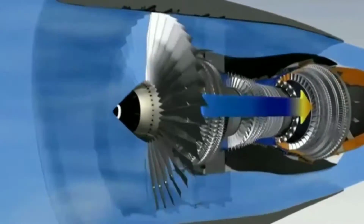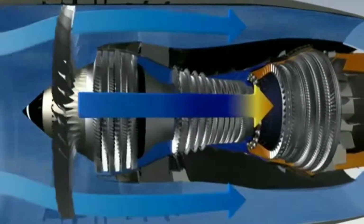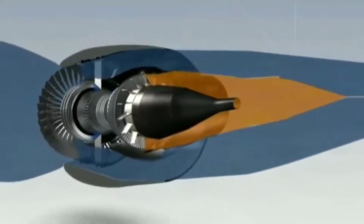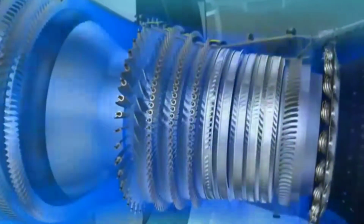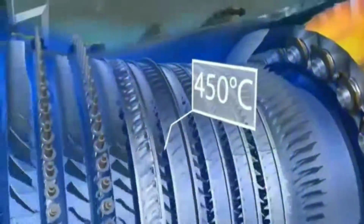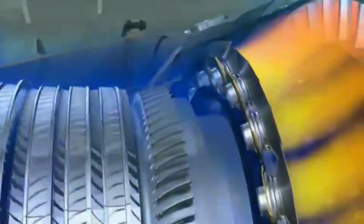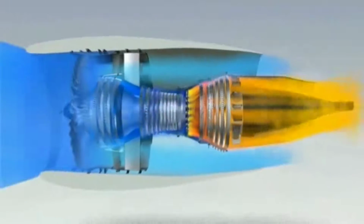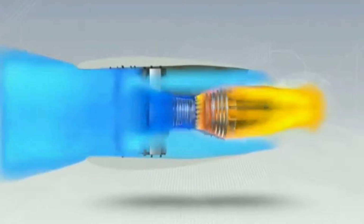A gas turbine engine works on the Brayton cycle, where the engine derives power from burning fuel in a combustion chamber and using the fast-flowing combustion gas to drive a turbine. A simple gas turbine is comprised of 3 main sections: a compressor, a combustor, and a power turbine. The compressed air is mixed with the fuel and burned under constant pressure conditions. The resulting hot gas is allowed to expand through a turbine to perform work.